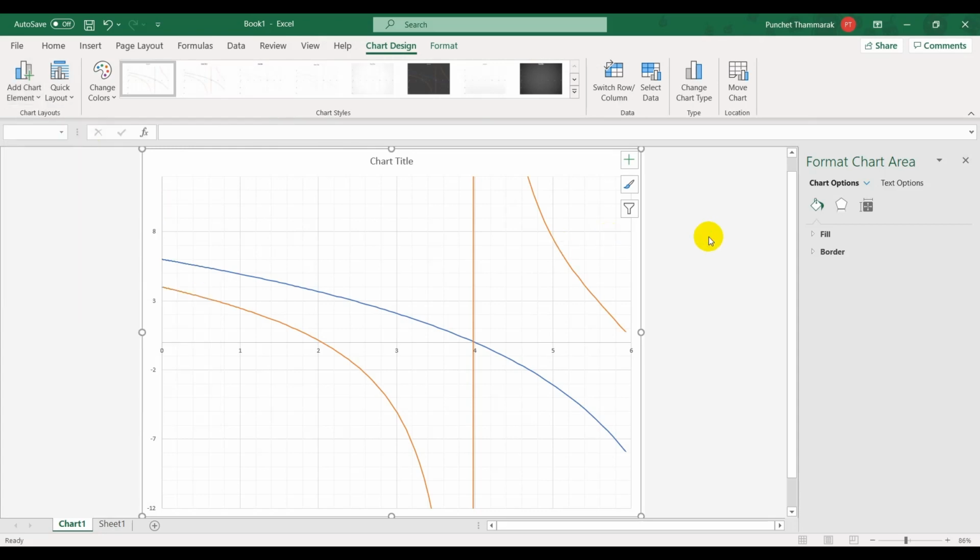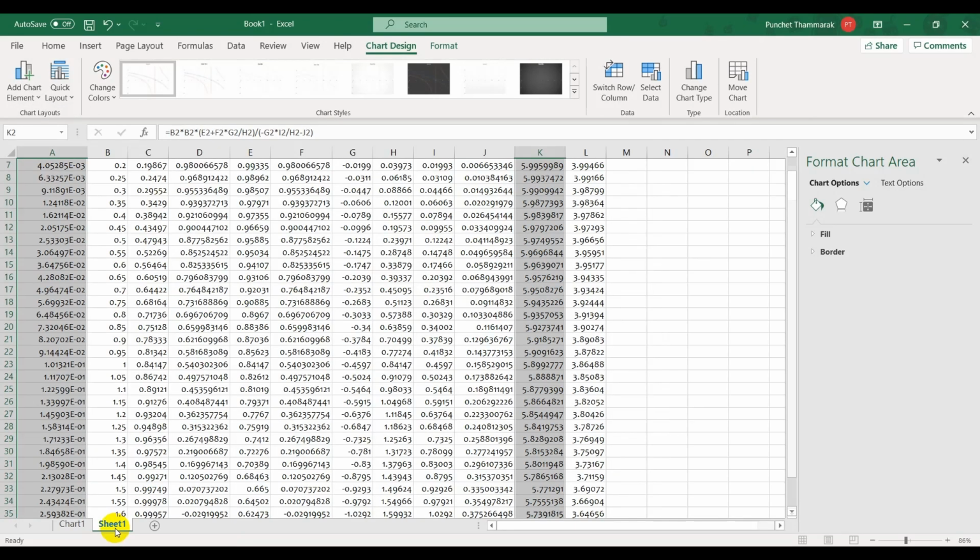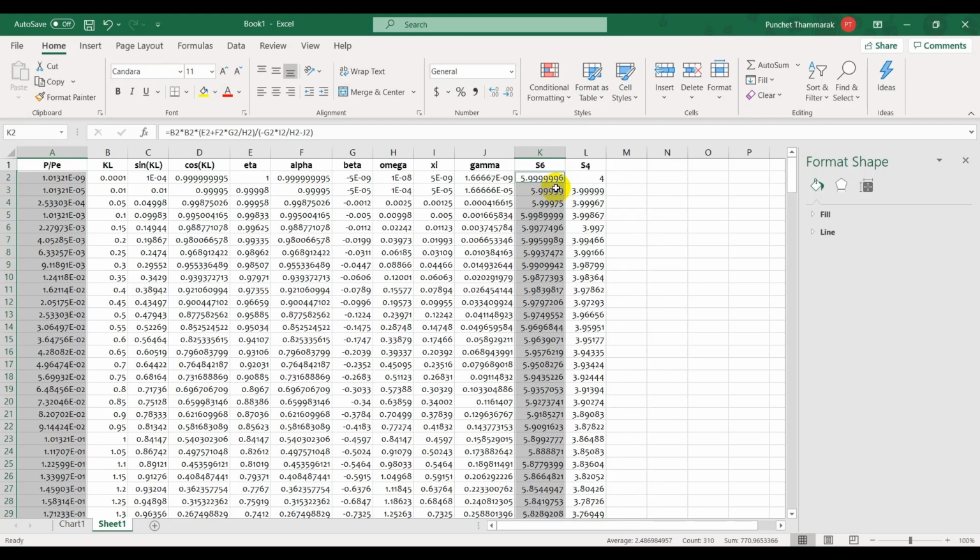Okay, right. Along with the table there, then you can perform structural analysis because you will know the PO/PE ratio. So the axial force in your member will be determined. In structural analysis, in many cases we don't know this ahead of time. We need to perform some sort of iterative calculation.